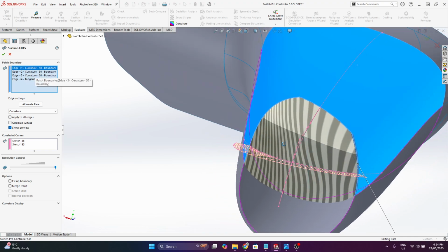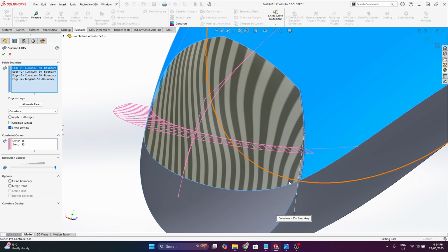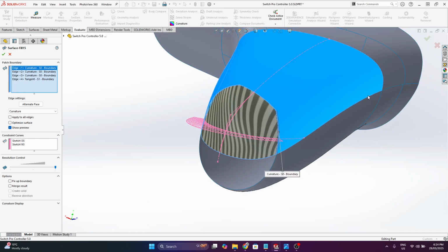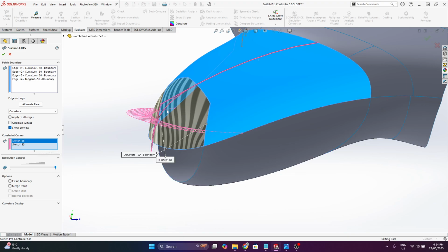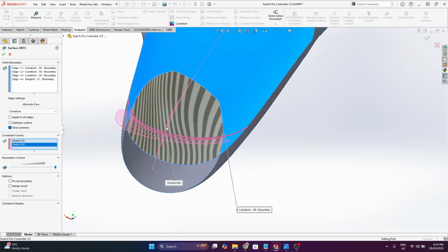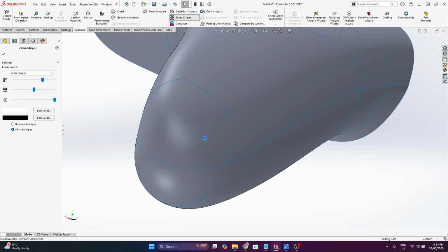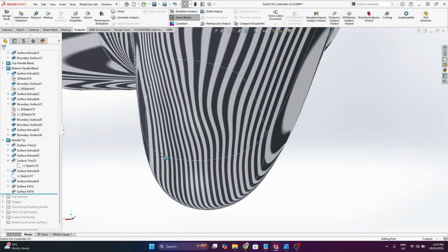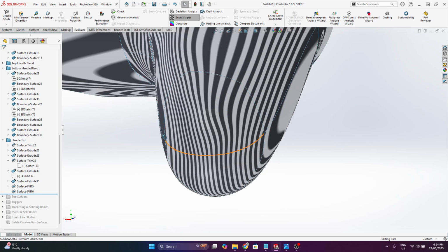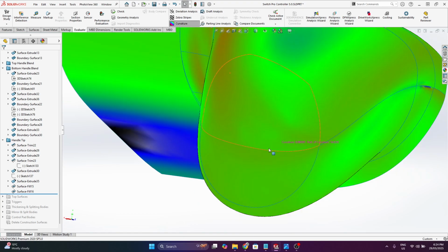But yeah, I used, you know, three of the edges that were produced from the surface trim, and then this kind of just general tangency 3D spline going around, and then some control curves in each direction perpendicular to each other to build this up. I do remember I had a little bit of trouble down here, and I believe it's still not totally perfect. Yeah, like a little bit of wobbling there, which I don't really want. But overall not too bad.